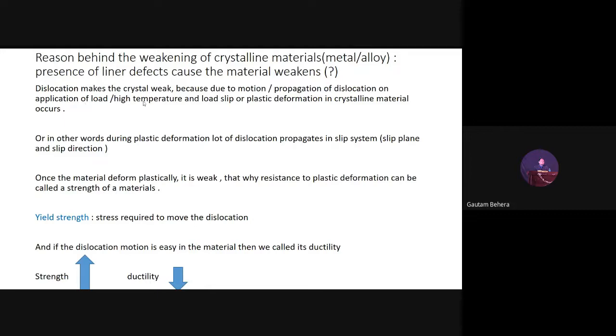And now the same thing which I have written. If we have a single crystal which is a perfect crystal, completely defect free, there is no dislocation, there are no grain boundaries, so it is a completely perfect crystal. The theoretical strength is very high, GPa level, gigapascal. But the materials we are using are basically polycrystalline in nature. They have grain boundaries automatically, they have dislocations. So due to the presence of these dislocations and grain boundaries, the crystalline materials become weaker, the strength reduces threefold.